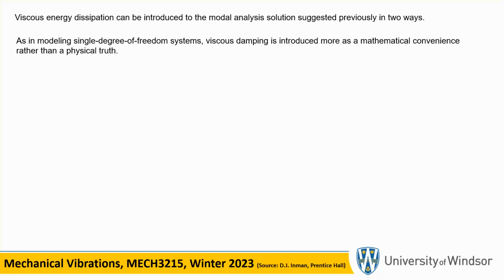So what we did instead, in those cases, we came up with an equivalent viscous damping model which replicated that Coulomb damping in the sense that the energy dissipated per cycle was the same. Going with that approach, we can still solve linear equations, but it inherited stuff from the Coulomb damping in an approximate way.